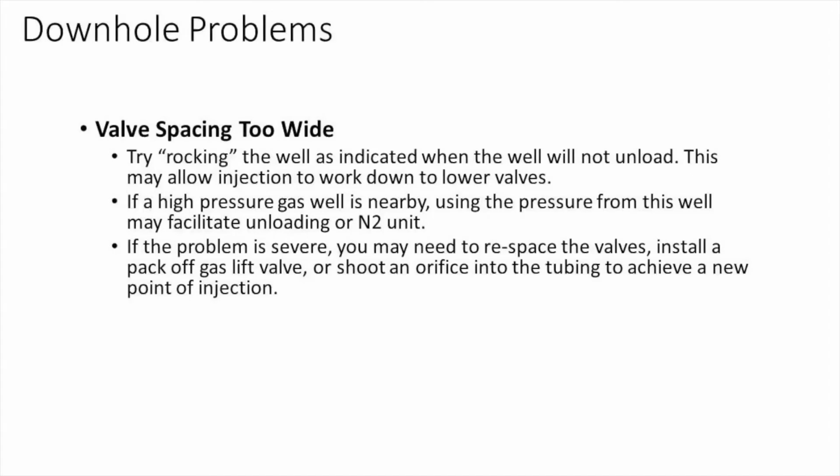Valve spacing too wide, valve spacing too high, goes back to the optimization side of deepening our injection point, getting a better system by a workover. Some of this you can fix without a workover, either through utilizing a secondary injection point like a nitrogen cryogenic or a membrane nitrogen unit, or swabbing the well. In most cases, though, it does require a workover to help improve the system of production.